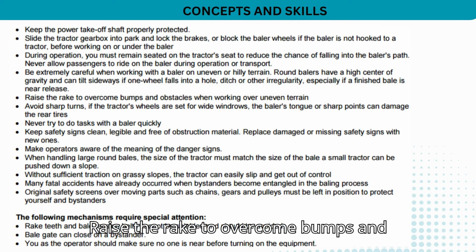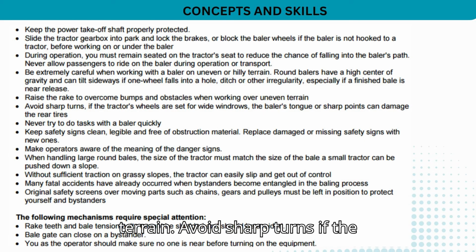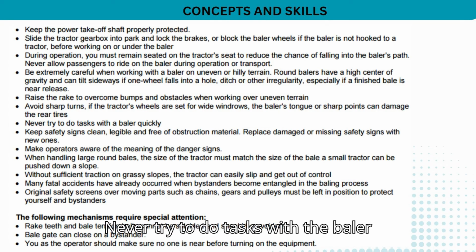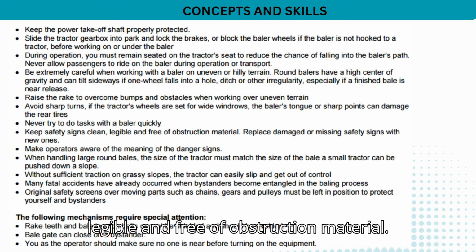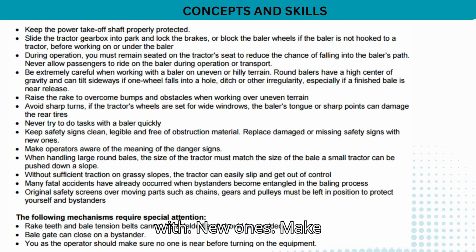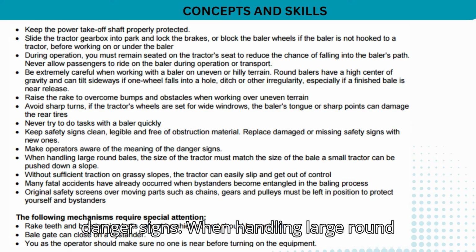Raise the rake to overcome bumps and obstacles when working over uneven terrain. Avoid sharp turns. If the tractor's wheels are set for wide windrows, the baler's tongue or sharp points can damage the rear tires. Never try to do tasks with the baler quickly. Keep safety signs clean, legible and free of obstructing material. Replace damaged or missing safety signs with new ones. Make operators aware of the meaning of the danger signs.